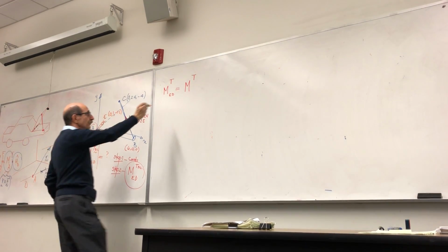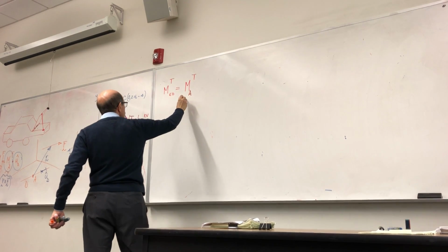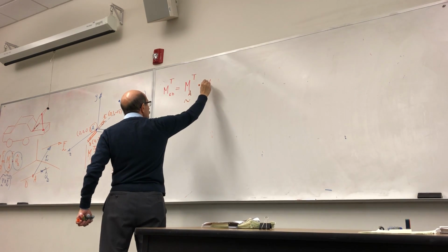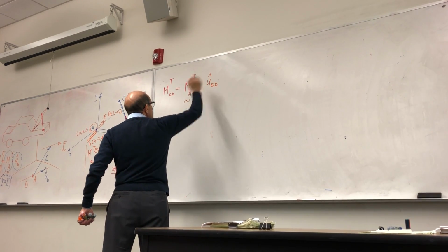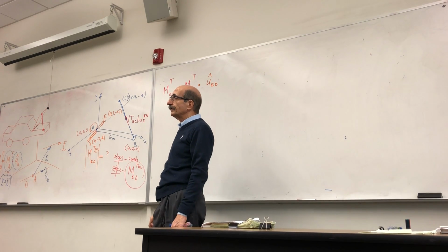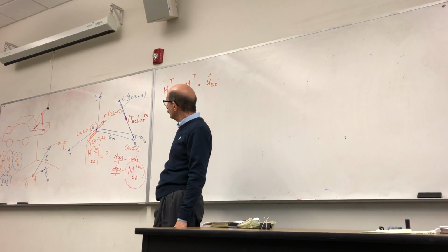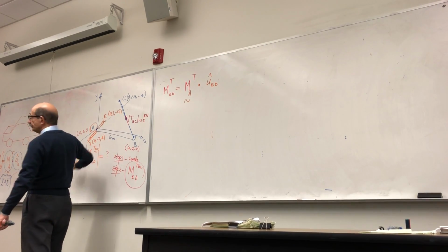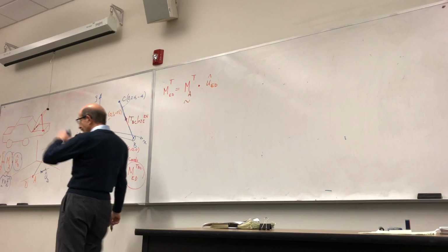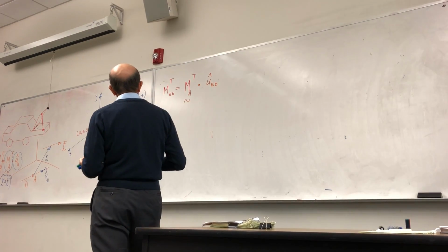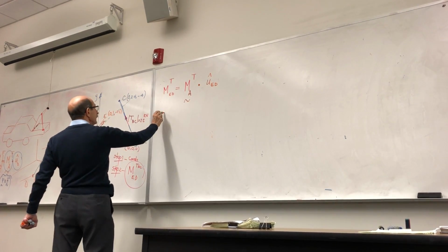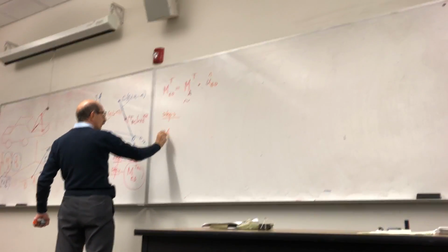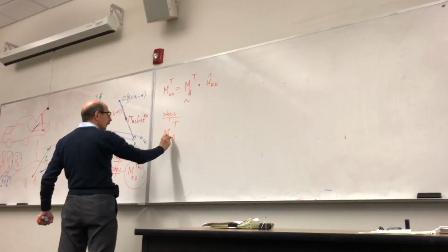So I will consider moment about A. Then you need to find a dot product of that and the unit vector of ED. Okay? So we are choosing between any point along this line, so it would be E, A, or D. And we'll see why A is the best in more detail. So as the next step, step 3, what do you need to do? Find the moment of this force about A.